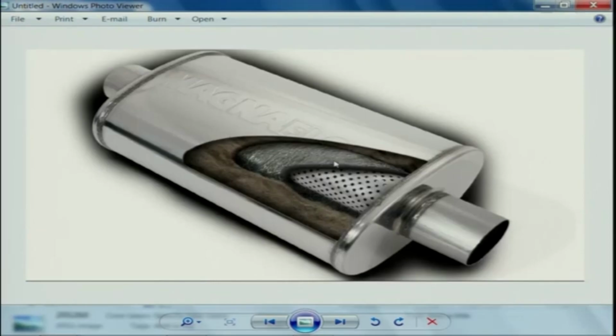So, basically this is a fully perforated muffler, but the annular area is also filled with absorptive materials. So, it is fully dissipative. The crucial idea is that the perforated pipe acts like a guide. It does not allow the flow to expand out freely, and it interacts with the annular cavity, and that is what happens. So, this is a straight through muffler with the least pressure drop, and the flow noise that I was talking about will not be there.